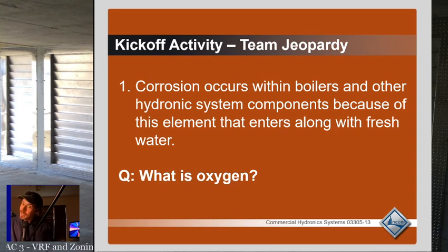Which never happens. But this is always my chief complaint with hydronic systems. You want to be very careful, and you should do the best job you can when you're doing a boiler or chill water system, because the more leaks there are, the more problems you have with the system, the more it corrodes, because every time you have to repair it, you got to open the system up.